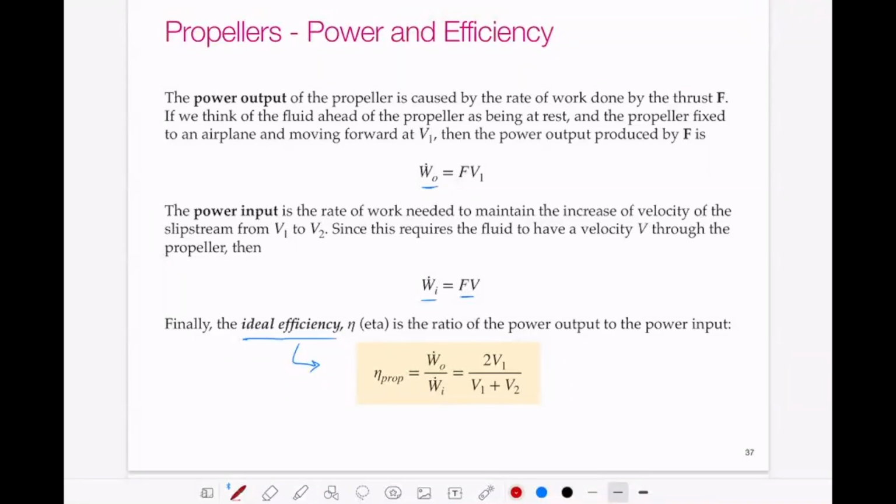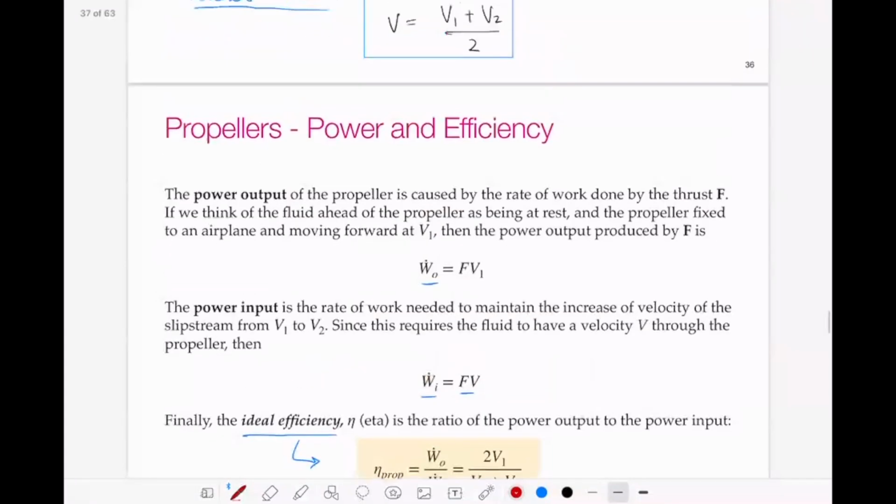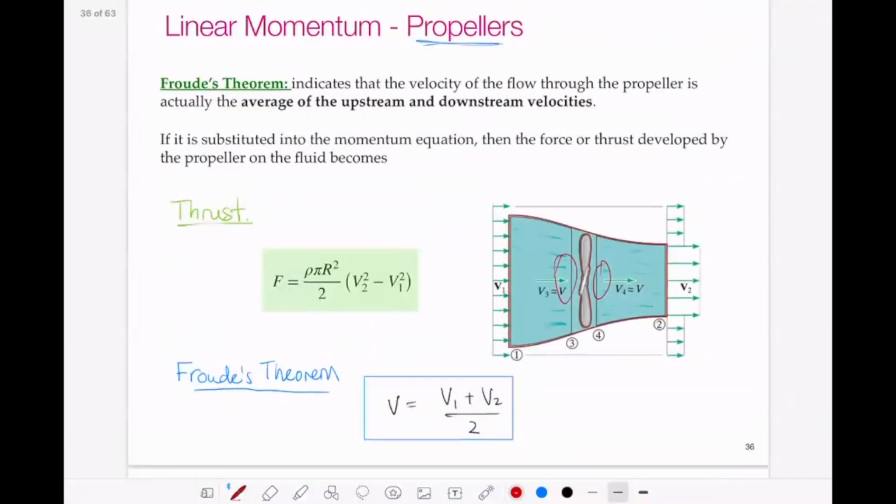So if we look at this equation and ask how we increase the efficiency, we can increase the efficiency by getting useful work without changing the velocity of the stream as much. If we imagine, maybe scroll back up here, that we had a control volume and our velocity input was equal to our velocity output, and we were able to harness some sort of thrust out of that, that would mean we were able to get some kind of thrust without actually changing the momentum of the fluid.